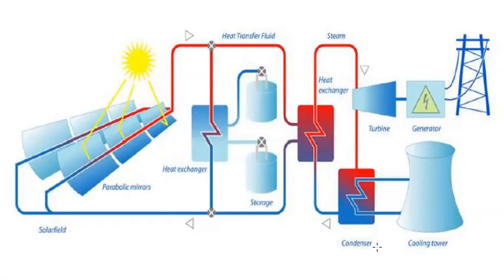The efficiency of a solar thermal power plant is the product of collector efficiency, field efficiency, and steam cycle efficiency. The collector efficiency depends on the angle of incidence of the sunlight and the temperature in the absorber tube, and can reach values up to 75%. Field losses are usually below 10% only. Altogether, solar thermal trough power plants can reach an annual efficiency of about 15%. The steam cycle efficiency of about 35% has the most significant influence.